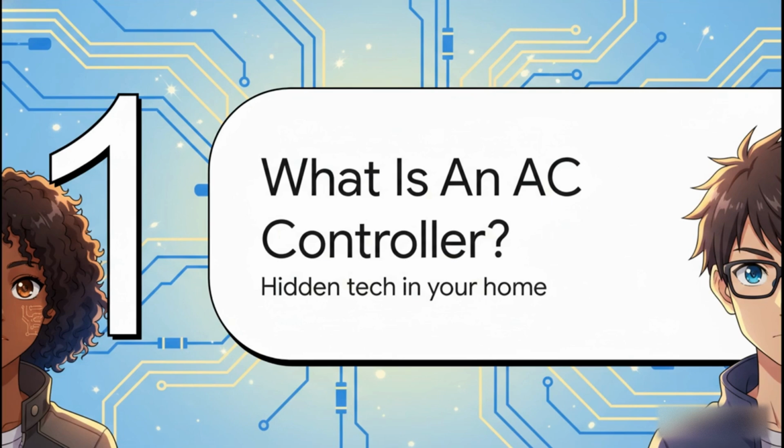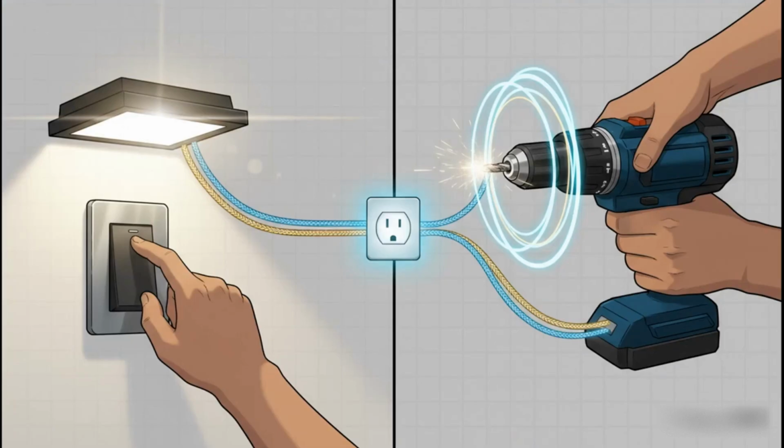It's one of those technologies that's pretty much everywhere, hiding in plain sight. I promise, once you see how it works, you'll start noticing it all over the place. Think about a standard light dimmer, right? You turn that knob and the light gets brighter or fainter, nice and smooth. Or what about a power drill? The more you squeeze that trigger, the faster it spins. Both of those are using an AC voltage controller. The whole point is to manage the amount of power flowing from the wall to the device. You're not changing the type of power, just how much of it gets through.